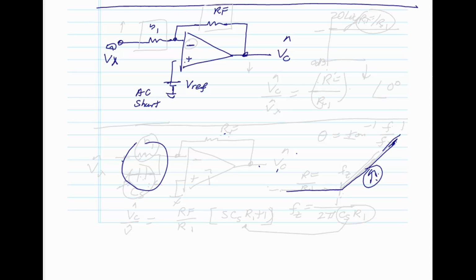So basically, into the op-amp is going to be this impedance divided by this impedance. So the output over the input is going to be, now forget the minus. We know it's a minus. It's inverting. So I don't always have to keep putting a minus in here.